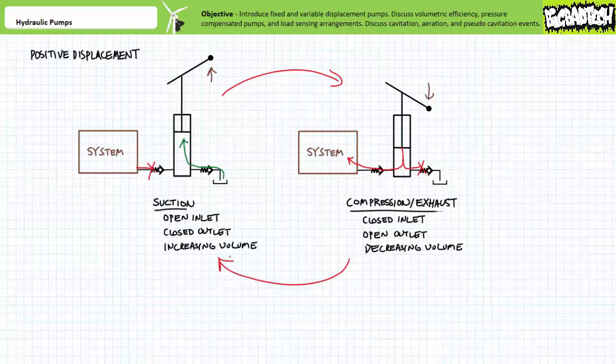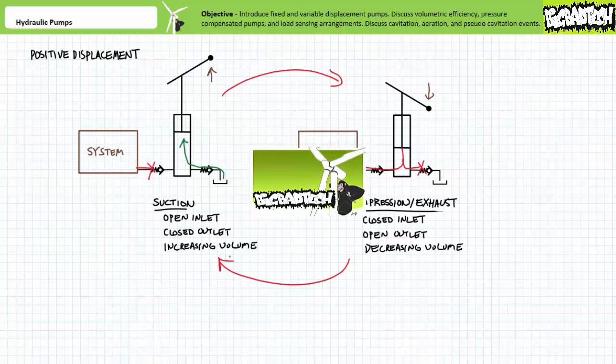Positive displacement pumps use close-fitting components and must properly filter and condition fluid to be pumped to a predetermined cleanliness standard if they are to perform reliably. Particulate contaminants may progressively abrade close-fitting components, leading to a loss of lubrication and sealing ability, as well as hinder efficient movement of the dynamically moving surfaces. Additionally, heat-degraded oil forms a sticky resinous byproduct known as varnish that can plug ports and glue ordinarily moving components together. We'll discuss fluid filtration and conditioning to prevent this from happening in other lectures.